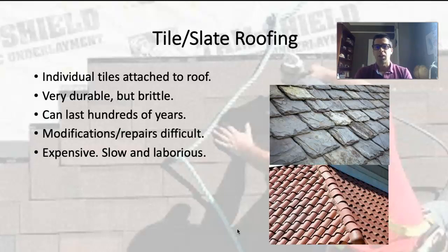It's very dangerous to tear these things off because it's so heavy. I would say there are also structural and framing considerations that need to be taken into account if you're going to apply one of these roofs to your building, because the material is so heavy, and over time it could cause a tremendous strain on the roof.